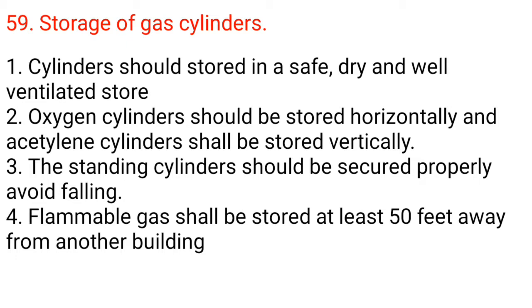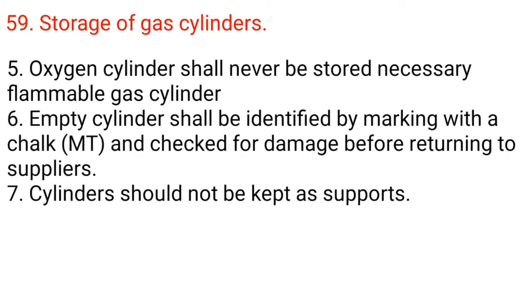Flammable gas shall be stored at least 50 feet away from another building. 5. Oxygen cylinders shall never be stored near flammable gas cylinders. 6. Empty cylinders shall be identified by marking with chalk and checked for damage before returning to suppliers. 7. Cylinders should not be used as supports.